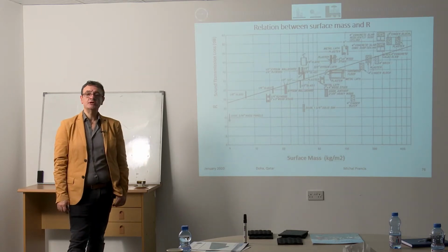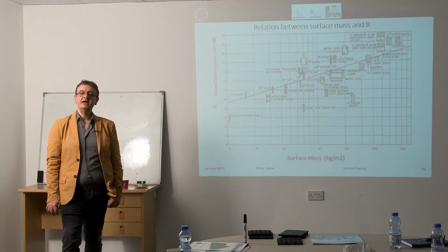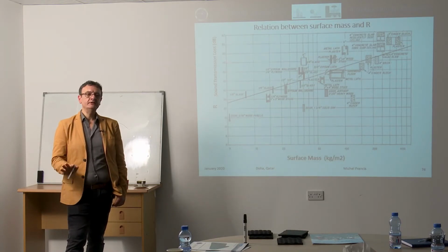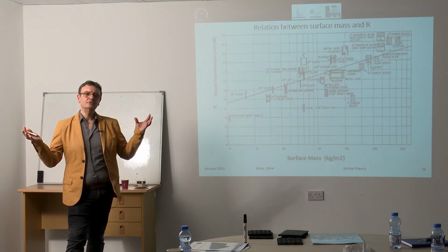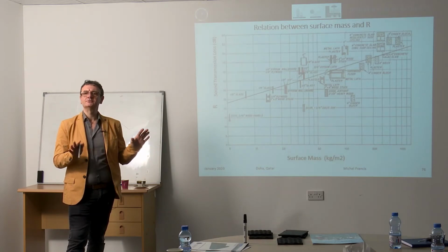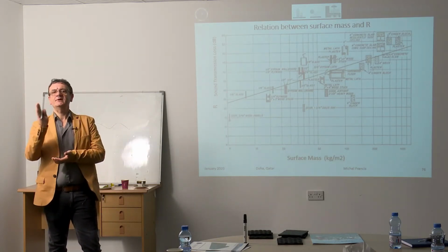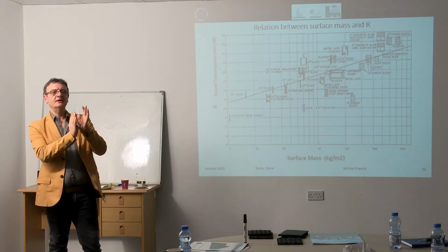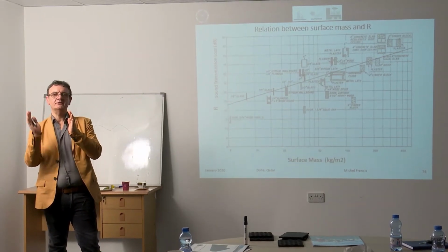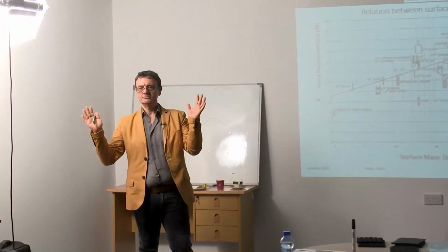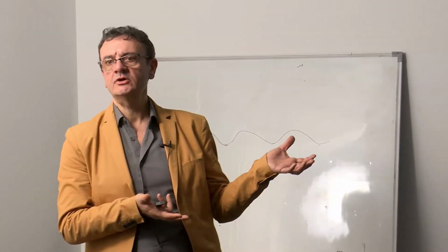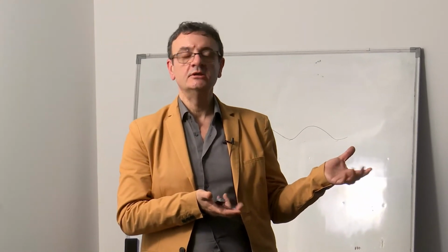In fact, when I want to estimate the STC rating of any assembly, and believe me, the assemblies given by architects will make you very old in very little time. They are stressful. So many layers inside, then in the middle an air gap, then outside another material, and then the cladding. So five or six layers. How do you know the STC rating? Unless you take that material and put it in a lab, you're not going to know the STC rating. But using the mass law, you can predict it.